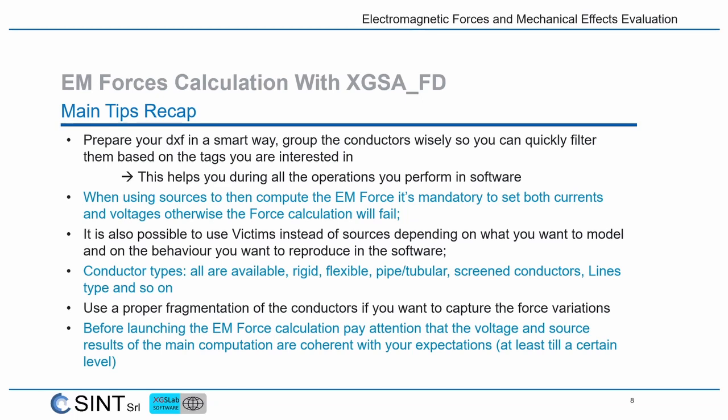Just it is important to use it wisely. It's very important to use a proper fragmentation of the conductors if you want to capture the force variations. Otherwise, you will just see a single value for a very long conductor, which will be, of course, averaged along the whole conductor, and this will make your calculation less meaningful, let's say, and less useful too.